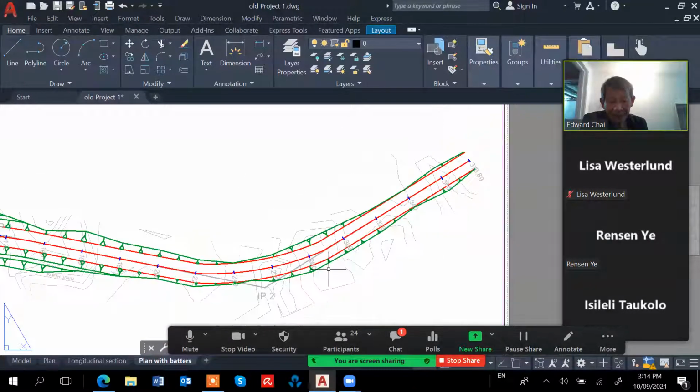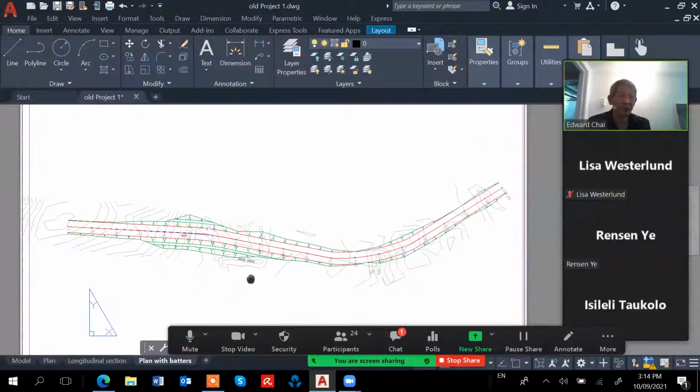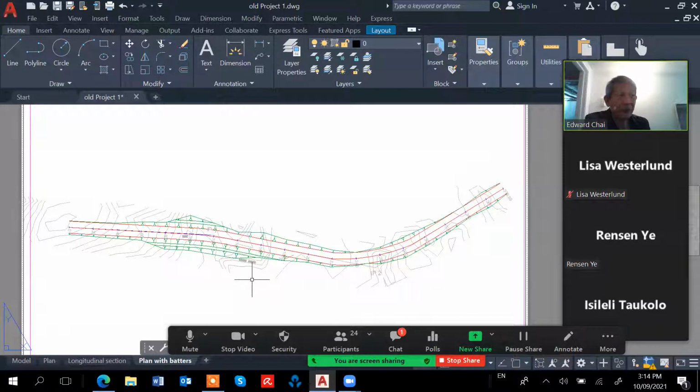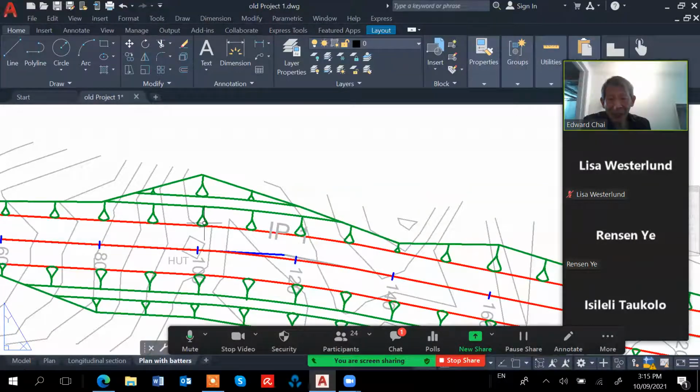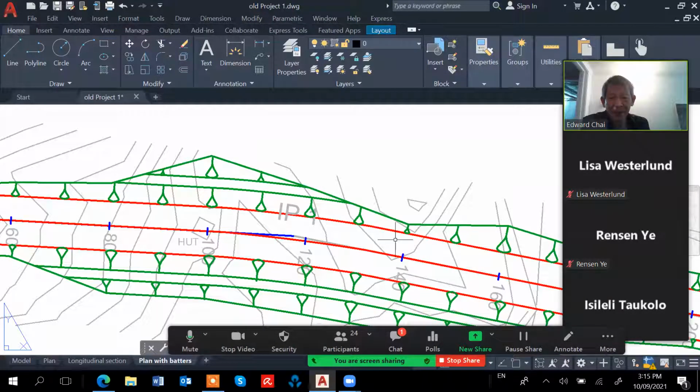So I think you just play around, especially rotate with reference. And then for the legend, you use the array path so that you don't have to rotate every one of them. If you array path, everything will be perpendicular to the center line, and then you just adjust the size by the scale. It's just SC, and then you can grab the bottom, move it a bit, and fill up the space.